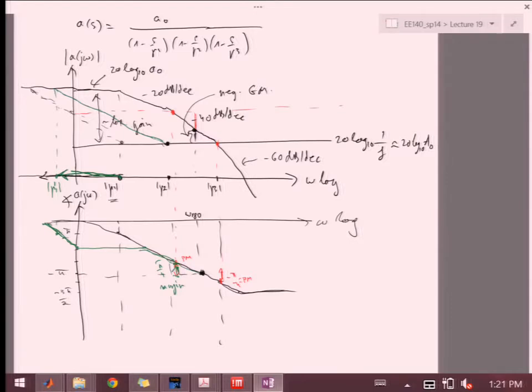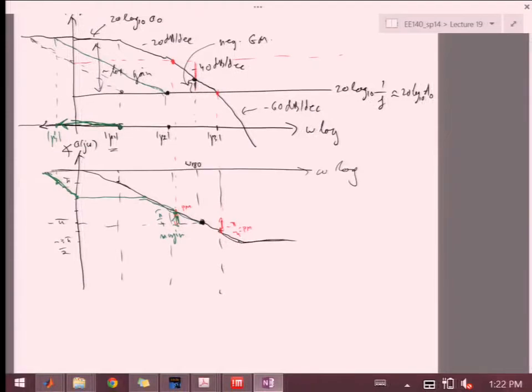Okay? So in that way, you have more bandwidth because now your unity gain bandwidth is at pole 2 rather than at pole 1. And you haven't added an extra pole. So because to shift pole 1 to this P1 prime is less capacitance added to the circuit because pole 1 was at a higher location to begin with. You can now do this a little bit more efficiently. Right. So, but how much should you shift?